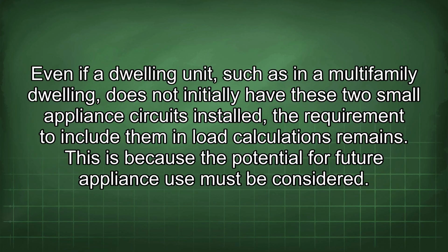Even if a dwelling unit, such as in a multifamily dwelling, does not initially have these 2 small appliance circuits installed, the requirement to include them in load calculations remains. This is because the potential for future appliance use must be considered.